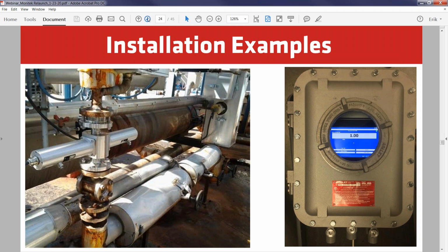This is an example that I kind of chuckled at yesterday. I said this is an example of how you don't want to mount our optical devices. If you see that sensor that's mounted on that pipe, right off the bat I see an issue where they have a little sight glass underneath it that will let ambient light come up. And if this was a scattered 12 degree or 90 degree analyzer, that extra light coming in, bouncing around and scattering, if the sun gets it just right, will actually create noisy sample results or elevated results that shouldn't be there,